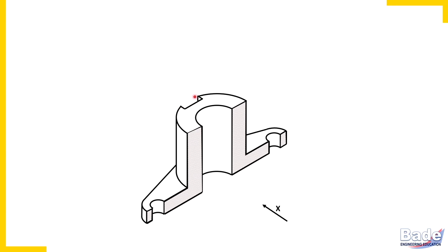So what we studied here: because of cutting, fresh surfaces get created. Those surfaces are to be shown by hatching lines. Some hidden details get exposed because of cutting, that is, those hidden details become visible. Some hidden details remain hidden even after cutting, for example this slot.